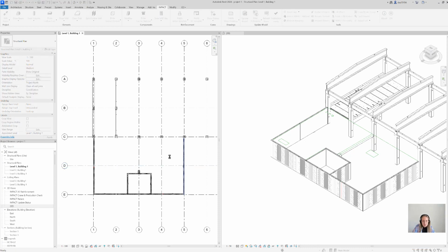So we're about to get some pretty good looking double walls here. We need to do the gable on this side. So I'm gonna say split double wall, select the wall, and now Impact is going to say that we need to select the location.